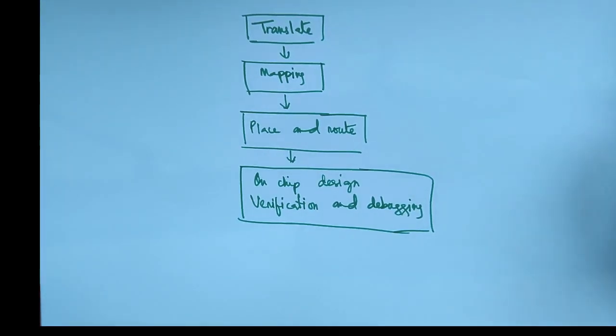The first thing, we have to write a code, and after that we are going to synthesize it. While synthesizing, it's going to translate the code into a netlist, which is a textual description of the circuit diagram or the schematic. Once we have done the synthesis, we are going to simulate it to verify whether there is any design error or whether the specification has been met.